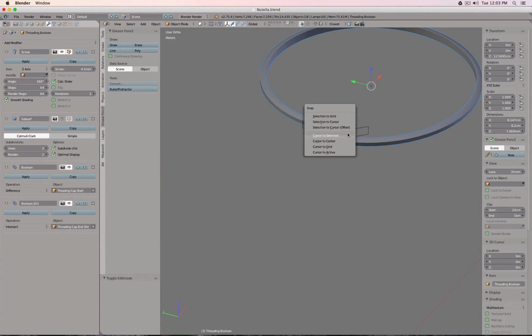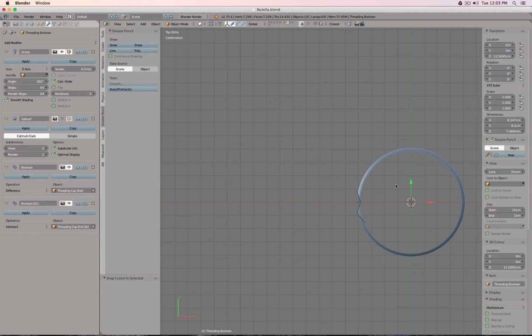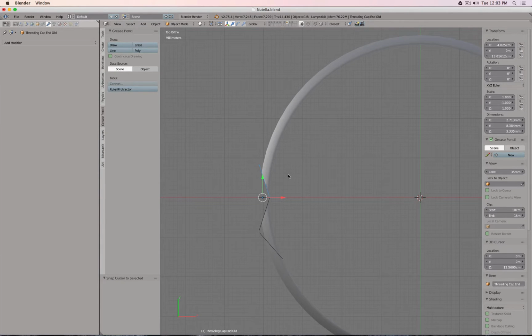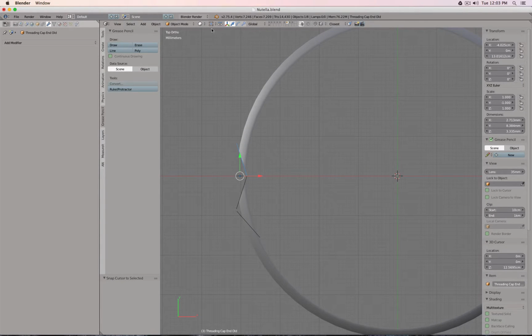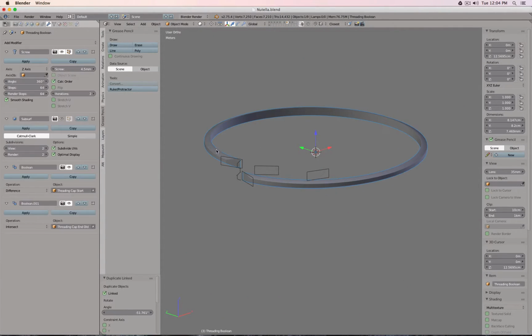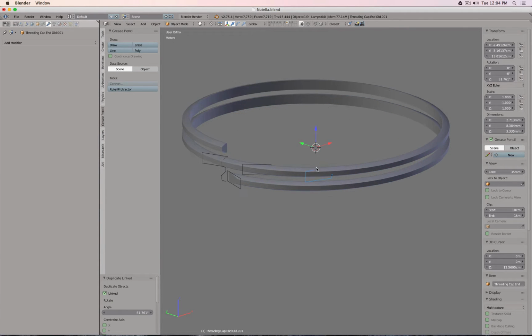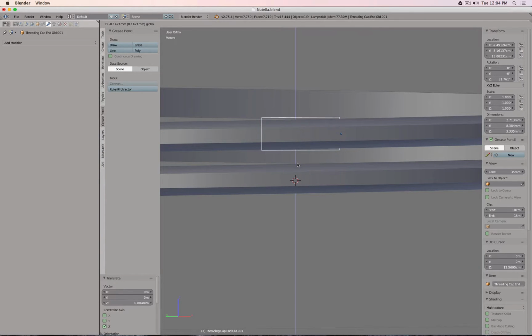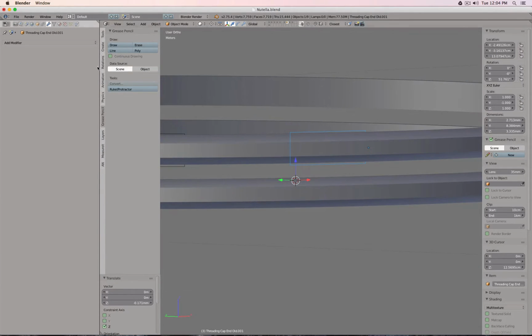So I switched my 3D cursor to the center of the threading, selected this geometry, and then switched to 3D cursor. And then with Alt D, I make a clone, and then R, you see I can rotate it around the center and it will always perfectly sit right where that threading is. And the only thing I have to do later is just adjust the height so it perfectly cuts through the object. That is very important.